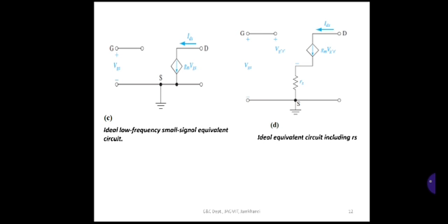If you want to draw an AC equivalent circuit for any network, you need to set the DC sources to 0, replacing them by a short circuit equivalent, then replace all the capacitors by open circuits. Then remove all elements bypassed by the short circuit equivalent introduced previously, and redraw the network.